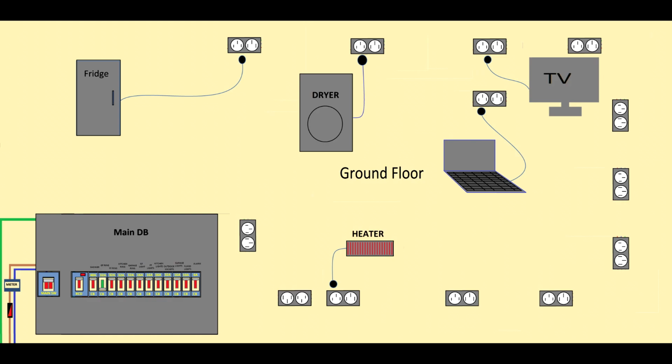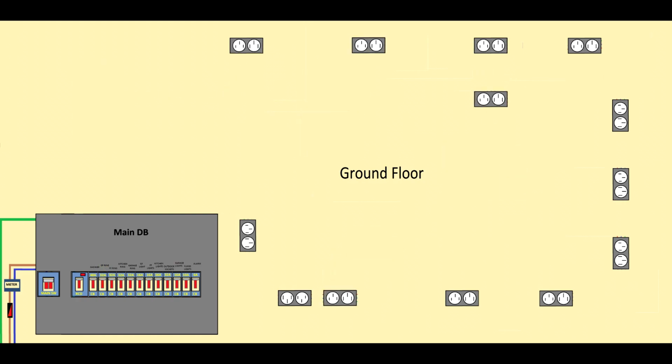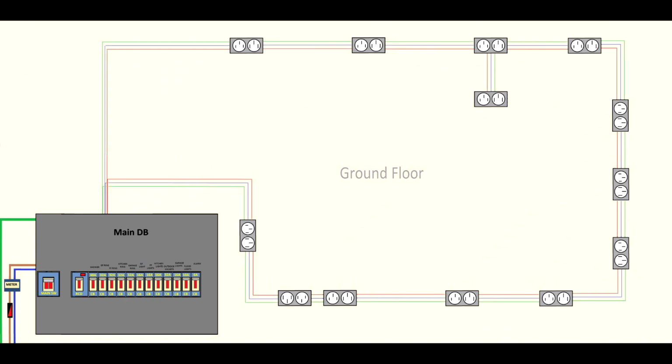I suggest that you unplug all the appliances from the faulty circuit, if you find it's the ring circuit, kitchen, whatever it is, and then you enable the circuit breaker again. If the circuit is okay, it means one of your appliances is broken. If the circuit trips the RCD again, then you have to take one step further and start investigating the ring circuit to find out what damage might be inside the wall, or burned sockets, whatever it could be. You can have many surprises.